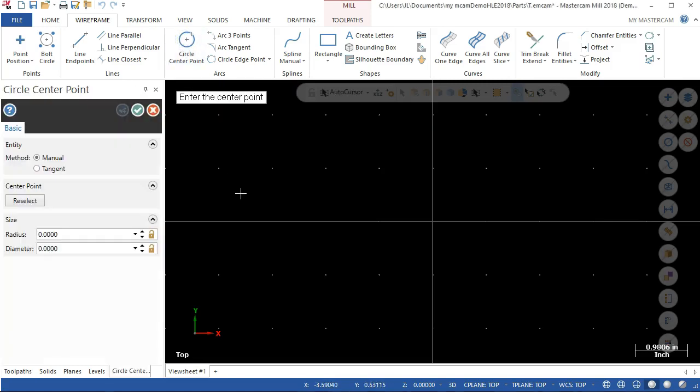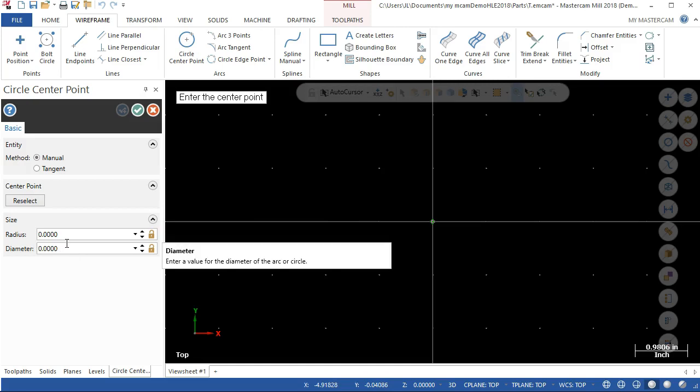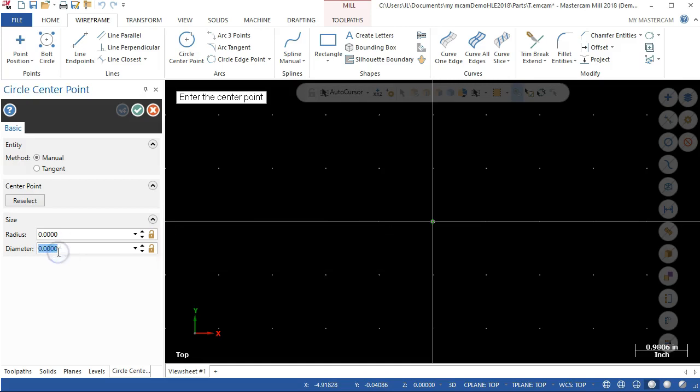Alright, circle and center point. So I said we had a 3/4 inch tool. Usually we're going to do bigger threads. So the advantage of the single point is it's not tied to pitch, where a multi-point we would have 20 threads per inch or 12 threads per inch or 14, 16, 18, take your pick, but you're going to have a more dedicated. So let's say that I want a diameter of 1 1/8,